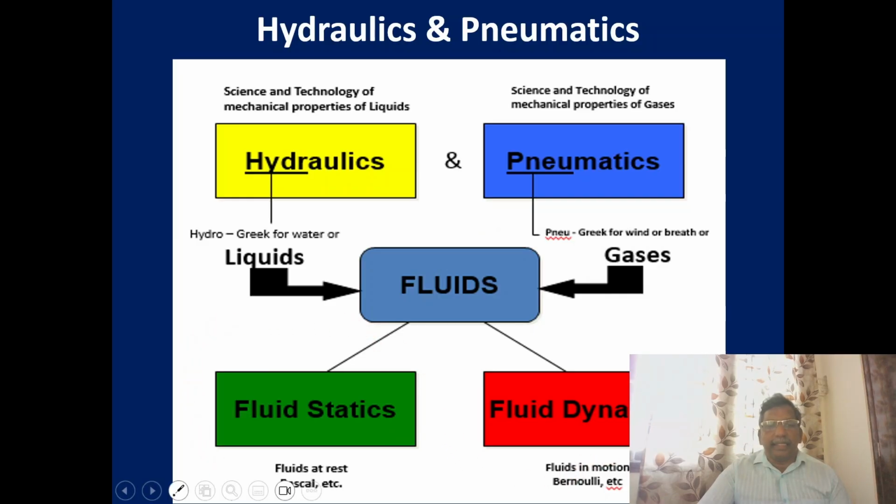What we discuss in fluid mechanics is under static, under rest. When under rest, we call it fluid statics. Under motion, we call it fluid dynamics, or fluids in motion. For example, if you want to measure the quantity of flow, the velocity of flow, or know the amount of flow, we can measure it with analysis equations, pitot tube, venturimeter, or orifice meter. But when we make use of this fluid to do some work, we call it hydraulics and pneumatics.